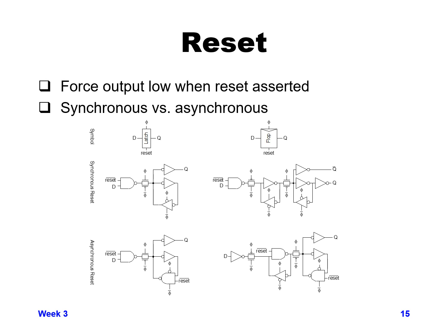And this NAND gate replaces the inverter that you normally would have had there, where D just goes into an inverter. It now goes to a NAND gate instead, and the other input to the NAND gate is a reset bar signal.